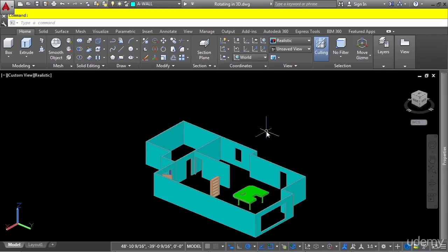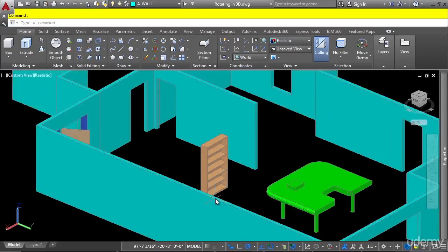You use the 3D Rotate gizmo to reorient objects in 3D space. During the operation of the command, you select the objects to rotate and specify the axis to rotate about. You can rotate about the X, Y, Z axis of the current UCS, or you can define a new orientation by placing the Rotate Grip tool on the face of a solid model.